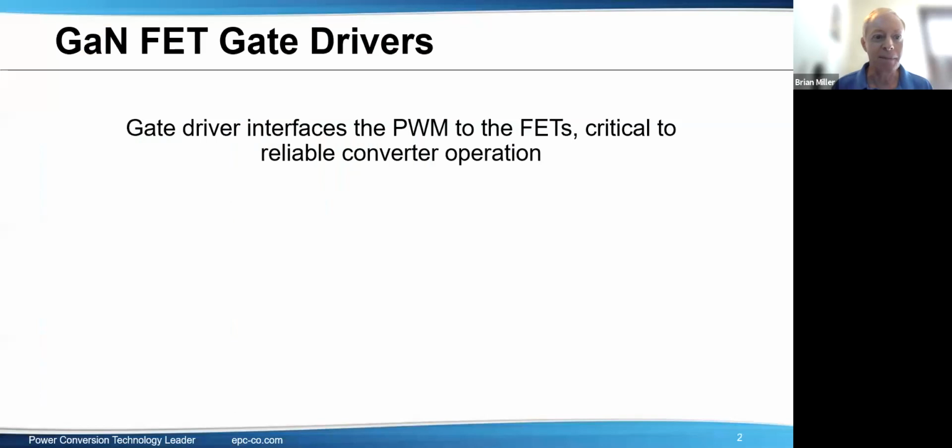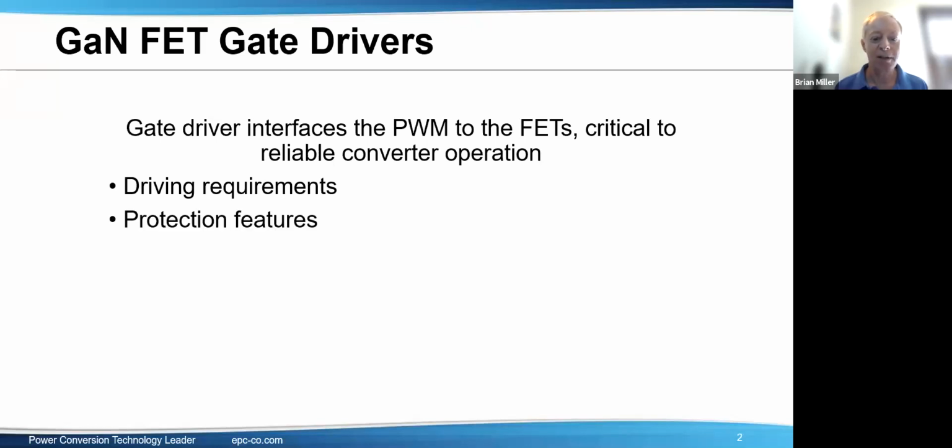To get things started, a little overview on GaN FET gate drivers. The driver is the part that interfaces between the PWM controller and the power FETs, and it's really critical for reliable converter operation. We'll go through driving requirements, what's needed for the GaN FETs to make them work best, and also protection features for the controller, features that protect both the output and the proper operation, and if various things need to be monitored.